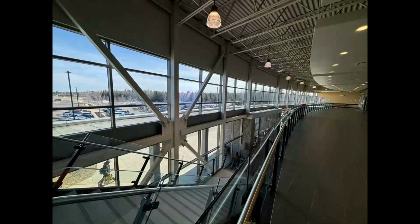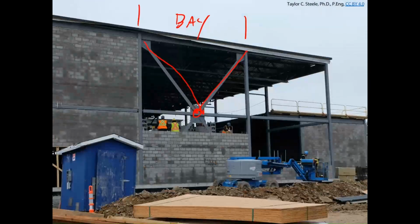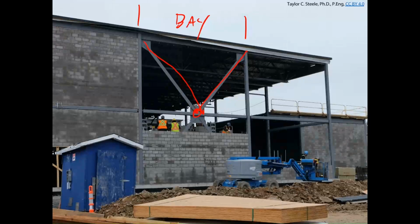Here we've got HSS bracing with a different kind of connection to the gusset plates here. So we can see in this image, we've got HSS that are quite sizable with big gusset plates. Here we've got flat bar stock used as tension-only bracing. And here we've got HSS members. In this case, they would be tension and compression bracing. Okay, so HSS are very commonly used for bracing members. They look nice, especially when they're exposed architecturally like you've seen here. Flat bar bracing is kind of ugly, hence why they're burying it within this masonry wall for this structure.